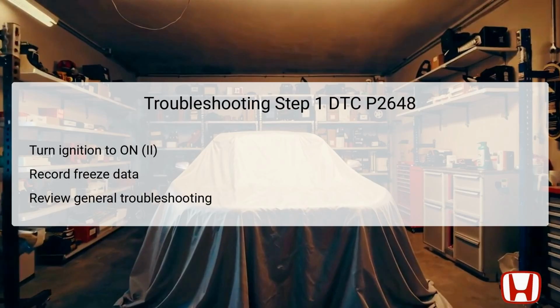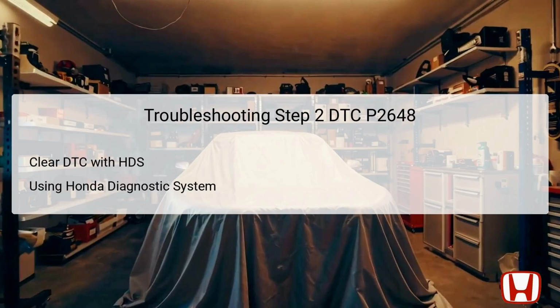The second step involves using the Honda Diagnostic System (HDS) to clear the DTC. This process resets the vehicle's onboard computer, allowing for a fresh start in diagnostics. By clearing the error code, you can check if the issue returns, confirming whether the problem is persistent or intermittent.